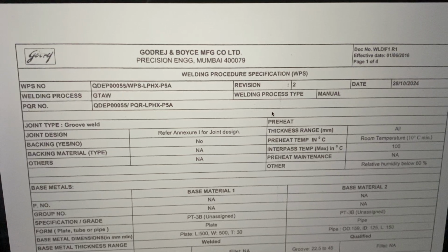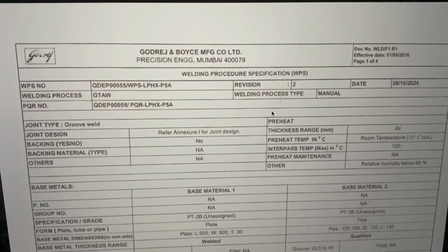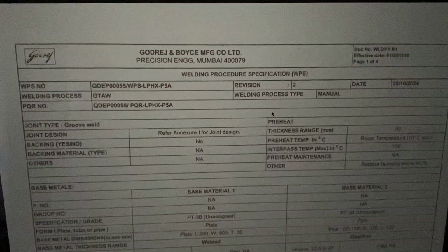And does this preheat require maintenance, or in other words, is it the post heating? And how much time shall this preheat be achieved? That means as soon as the temperature is arrived, like in a heat treatment furnace, our annealing temperature or stress relieving temperature is, let's say, 900 degrees centigrade or 600 degrees centigrade. As soon as your material reaches 900 or 600, you don't stop it, because after that you want to really achieve the uniformity across the thickness, so you have a soaking period.